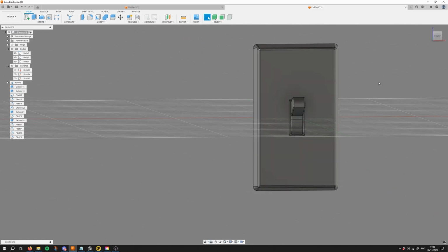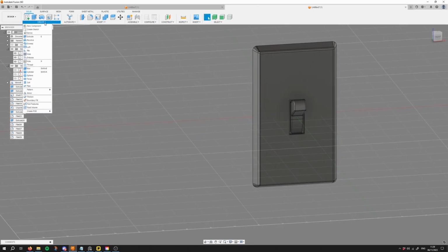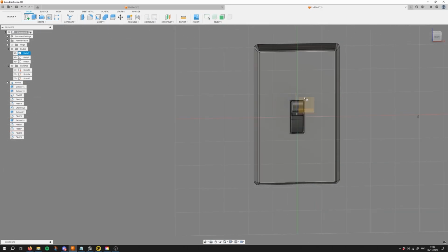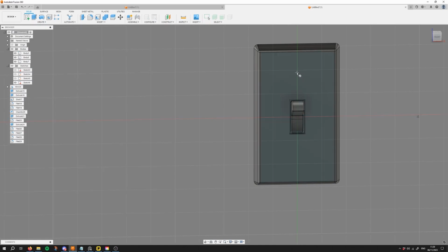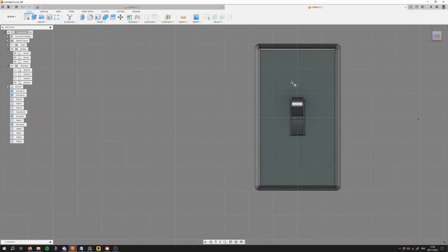Let's go. To create a little screws, you can either create a circle or a cylinder. I have it set to Shift R. We can try it like this. Select your face again. And if you want it to be exactly in the middle, it will usually snap to it. And if it didn't, you can make sure you have your triangle and drag it down. It'll keep the same axis from the middle point right here.